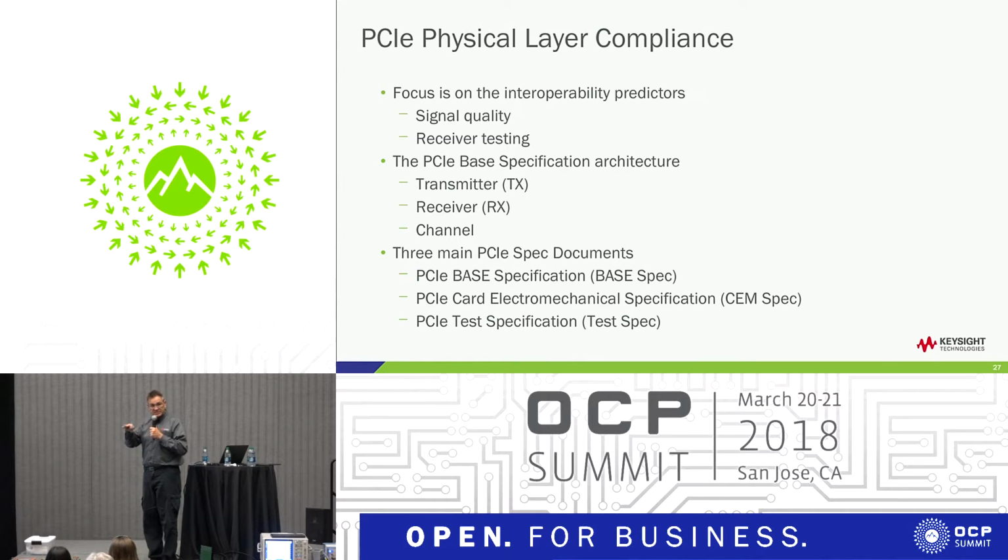The specification for PCI Express is divided into a number of parts, and each of those parts reflects a specific kind of conformance requirement that is comprehensive. You have a transmitter specification, a receiver specification, and a channel spec, so each of these can be tested individually. The theory is that if you have a compliant transmitter connected to a compliant receiver through a compliant channel, then by definition the system is compliant.